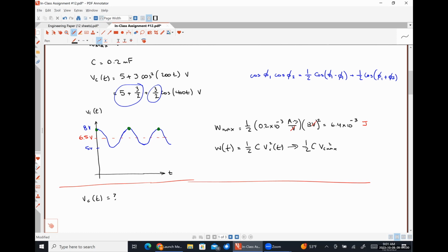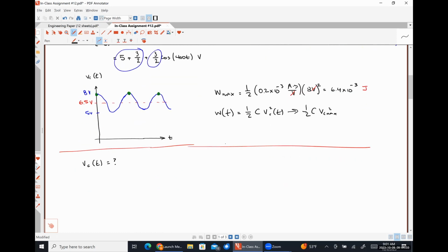So if we're trying to find our capacitor voltage, let's look at the information that we know. VC of 0 minus was 0 volts. IC of t was 8e to the negative 100 t milliamps. So my first question is, which of our 4 relationships should we use? The second one, absolutely right. We're trying to find voltage, so we should use the one that says voltage is equal to stuff.